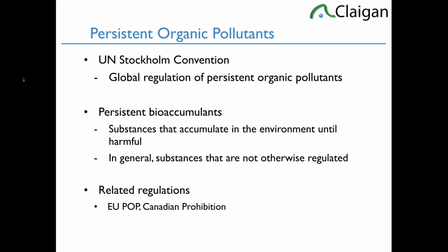One of the other ones is DECA BDE. It's the only polybrominated diphenyl ether we ever see. And the other ones we see are just because they're contaminants or breakdown products of DECA. The reason DECA is restricted under RoHS is not because it is a hazard, because it's not directly. It's because it breaks down relatively easily into NONA and OCTA, which are hazards to recycling workers. DECA itself is fairly non-reactive, which is very common with most flame retardants. To be a good flame retardant, you want to A, be happy with plastics and oil, so they like fat, and B, they don't oxidize or burn, so they don't break down very well.